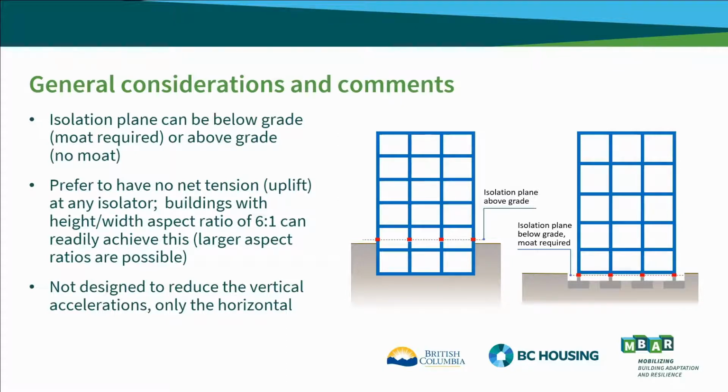Just for clarification, the seismic isolation system reduces the horizontal components of shaking, but the vertical shaking component is still there, similar to a fixed base building. But that is typically not the damaging component of ground shaking.